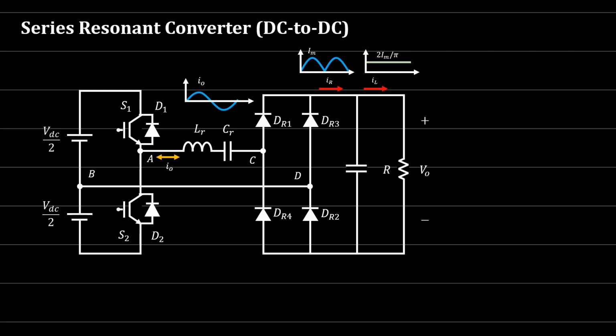Because we have to fix this converter working at this 1 kilohertz frequency, on this resonant frequency. You'll tell me, okay, what is the problem? We can just use an inverter, no problems, but the inverters are usually used for 50 Hertz frequency, right? The load is 50 Hertz or 60 Hertz frequency, not 1 kilohertz, not the resonant frequency.